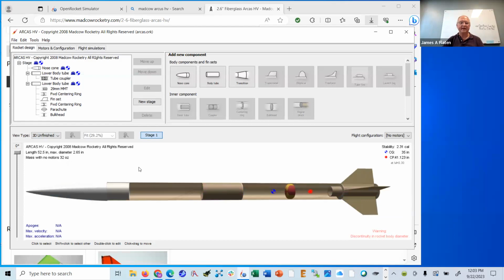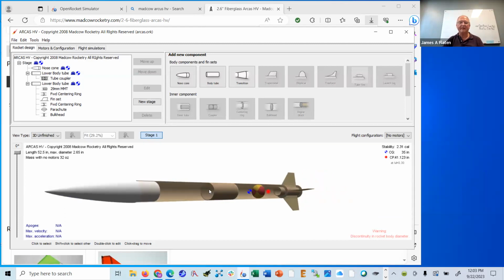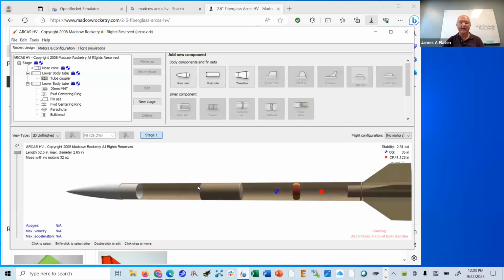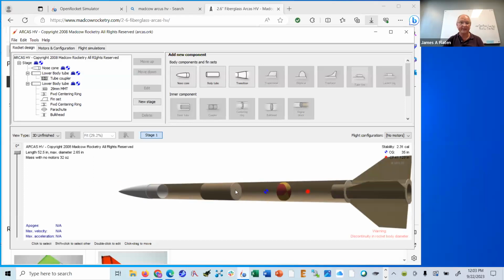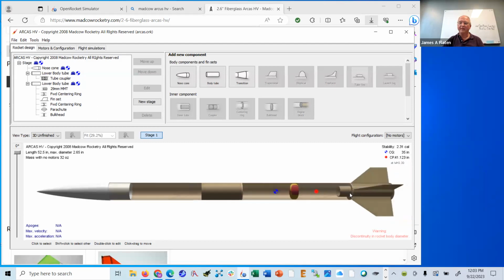In fact, let me look inside this rocket. I noticed that there's a nose cone with a shoulder. The coupler section, interestingly enough, apparently does not have a bulkplate on the top, but it does have a bulkplate on the bottom, as the model is currently drawn. This is intended to be a parachute of some sort. I would say that's not located in the right spot. That should be at the bottom of its section. I might fix that later. And then over here, I have the fins, and I have centering rings, and I have a motor tube. So I can see all of these parts.